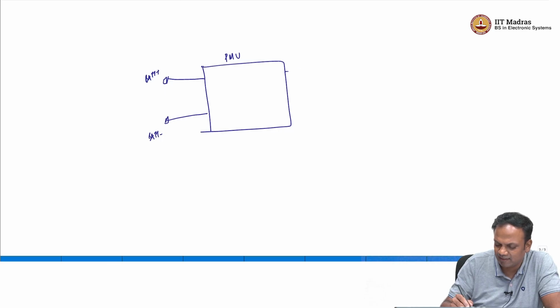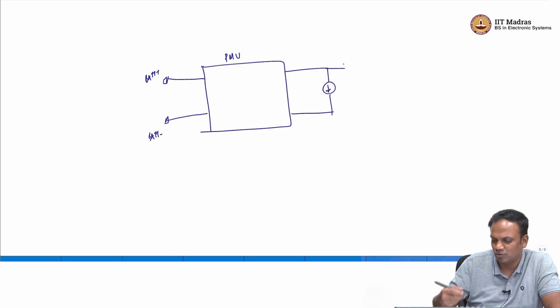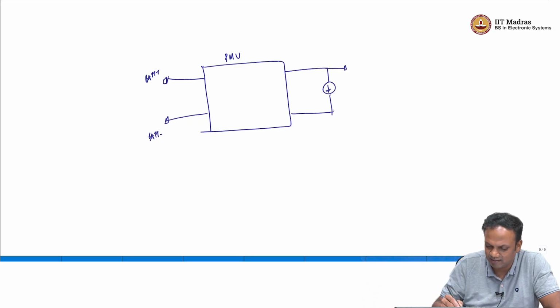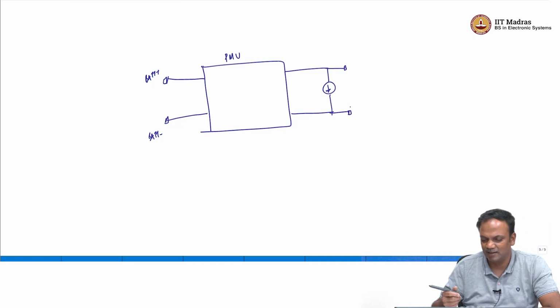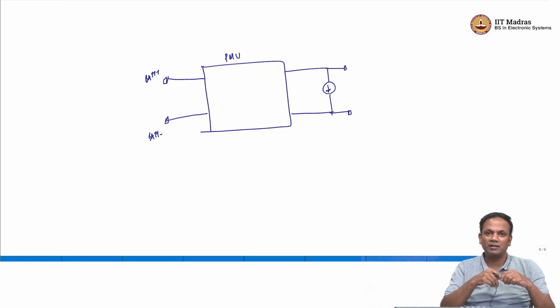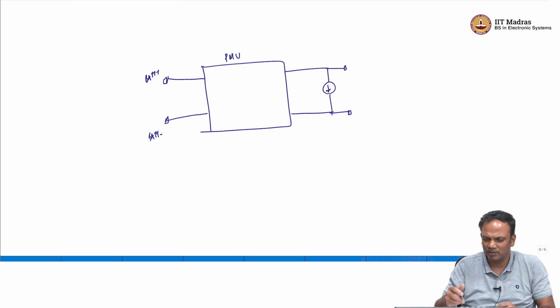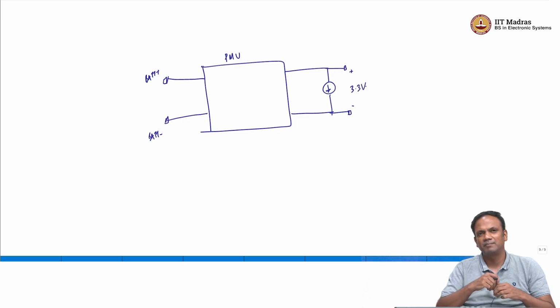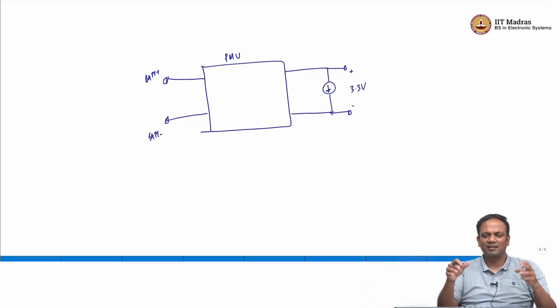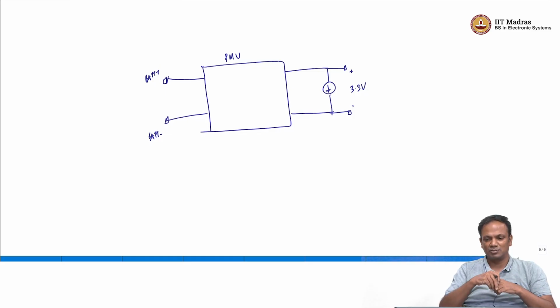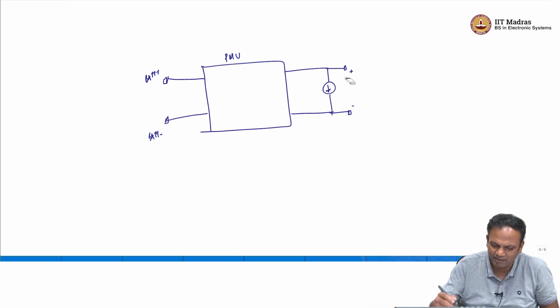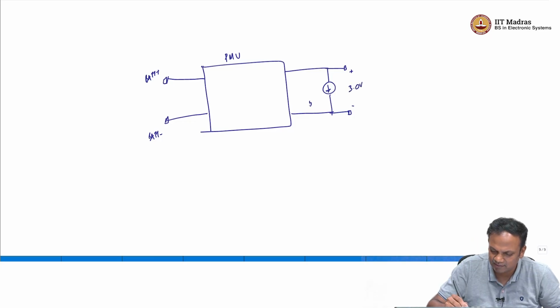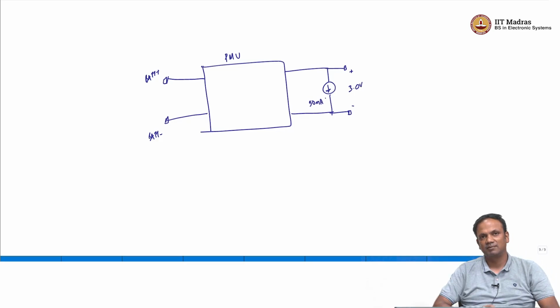Now, instead of driving the MCU, it is driving the RF. My connectivity system has an RF, and because I have to put out quite a bit of output power, I need a large supply voltage. So, what I would really like is a 3.3 volt supply, for argument's sake. Or let us say this battery supports up to 3 volts, so this also says give me up to a 3 volt supply. Now, let us say this is 50 milliamps of current.